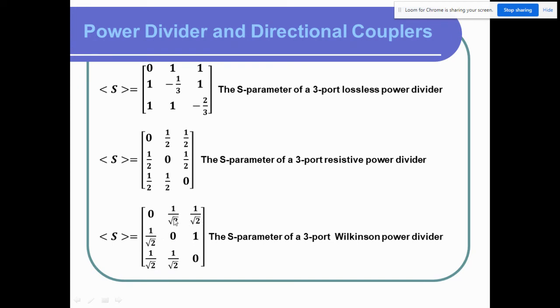So it means 0.707, or you can actually square it. If we square it, then you see half, right? Square it means the power. So this is half of the power, which can be split into two different junctions of the split. So there is no reflection and it can equally split the power.